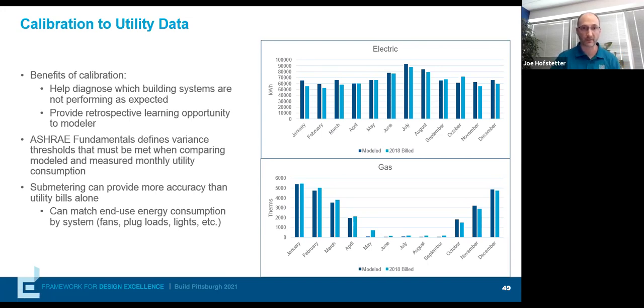Finally, calibrating. Maddie made a mention earlier about weather data and how we go off of an average. In the later parts of this tool, we can extend its usefulness into occupancy by calibrating it to actual real weather data, real world situations. After that first year of occupancy, we have that historical information available internationally, being able to pull the weather data of the last historical year.